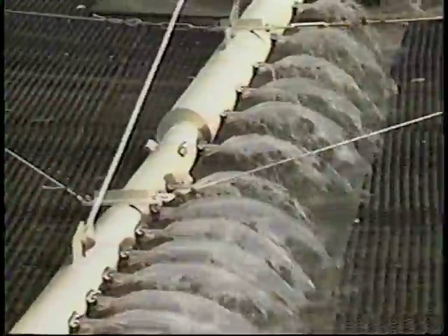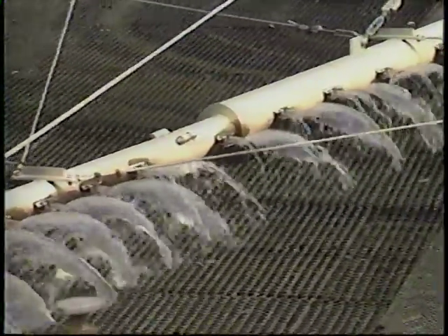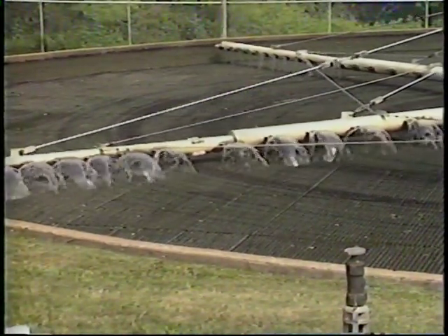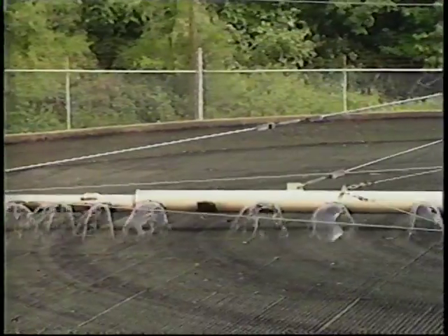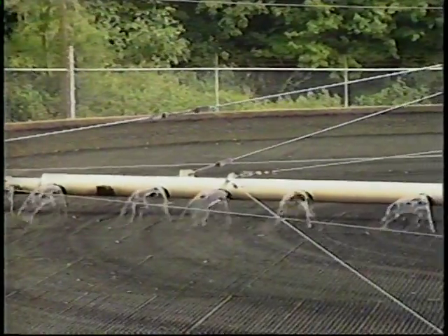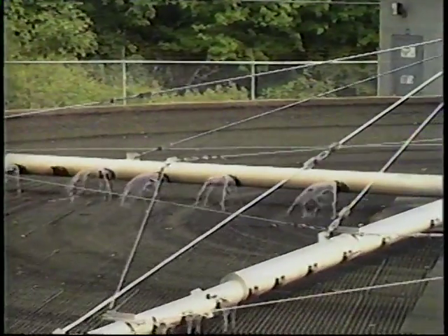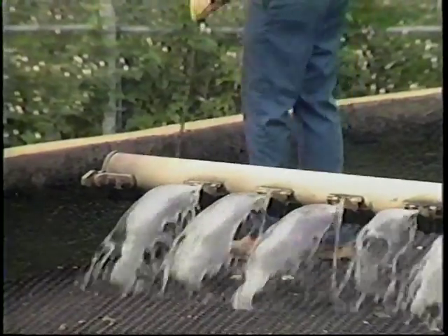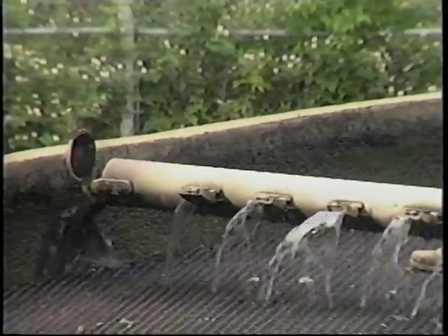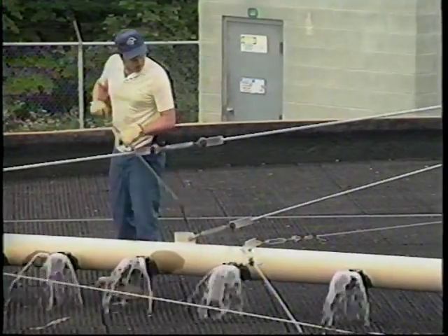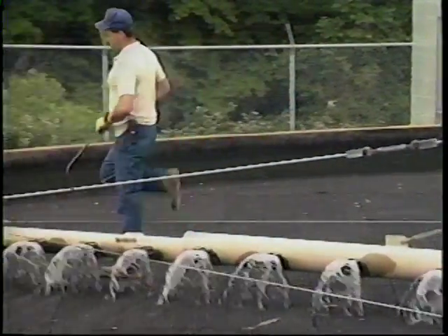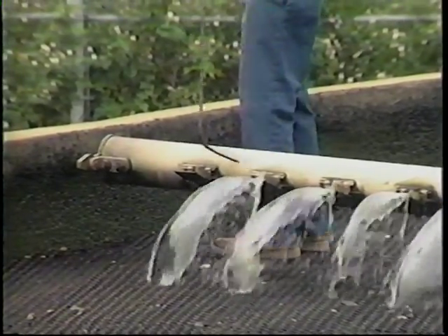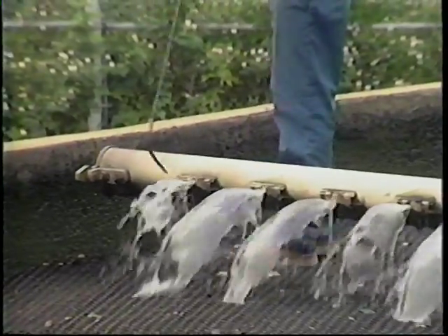The orifices are usually adjustable and are equipped with splash plates to evenly fan the wastewater over the media. The orifices are closer together as you get to the outer part of the distributor to facilitate an even distribution of the wastewater over the entire bed of media. In some cases, there may be orifices on the reverse side of the arm to act as reverse thrusters to control distributor arm speed. Most distributor arms have end plates that can be lifted to flush out debris. It is important to keep the flow through the distributor arm unrestricted. Keeping the orifices clean is important for proper operation of the trickling filter in both fixed and rotating distribution systems.